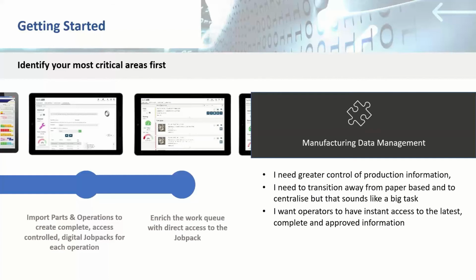So using electronic data deployment, it can ensure that the required information is available at point of use when it's needed. So the use of job packs, or the CT job pack as we call it in here, or a package of information through an electronic system, it provides the control of the data being used. It ensures the latest and up-to-date information, such as the correct NC programs being used. And it's all administered in the office and then accessed on the shop floor via encrypted files.